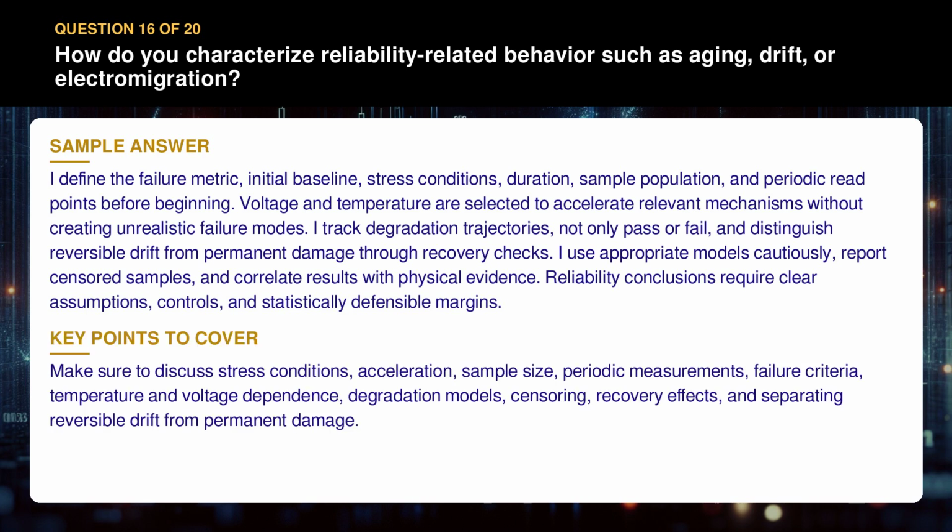Make sure to discuss stress conditions, acceleration, sample size, periodic measurements, failure criteria, temperature and voltage dependence, degradation models, censoring, recovery effects, and separating reversible drift from permanent damage.